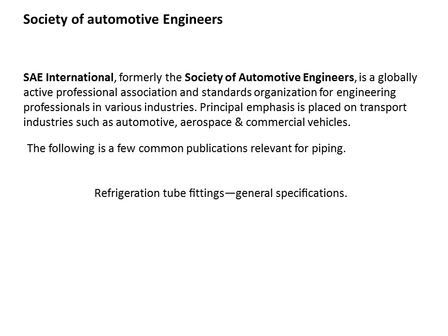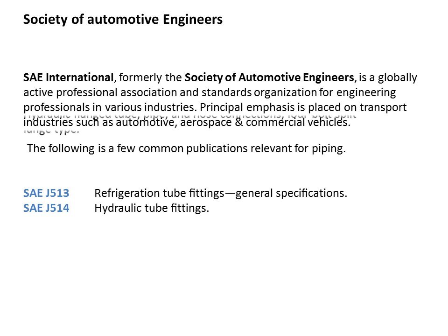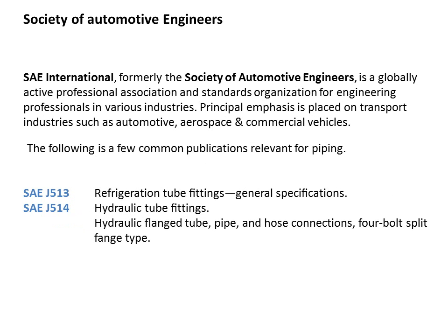Amongst them are refrigeration tube fittings, general specifications, covered in SAE J513. For hydraulic tube fittings, the SAE J514 standard is there. For hydraulic flange tube, pipe and hose connections, four-bolt split flange type, we have SAE J518.